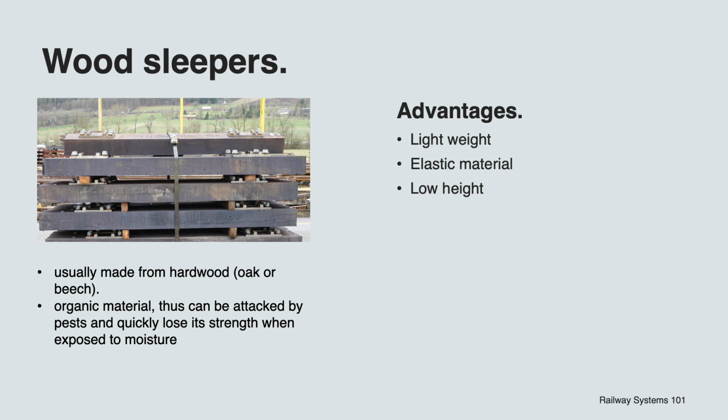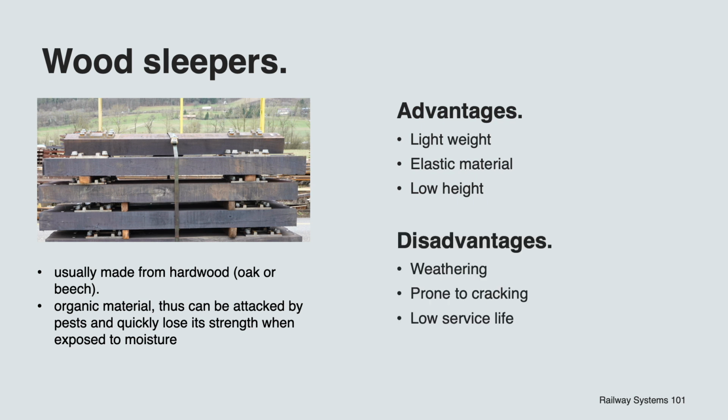Unfortunately, wood sleepers present a few disadvantages, for example, weathering. Despite the impregnation, wood sleepers are susceptible to weathering and they tend to lose their stability over a few decades. Cracking tendency: component failure can occur under very high loads. The incremental loosening of the fastenings under load, and the environmental impact due to the impregnation with toxins like creosote.